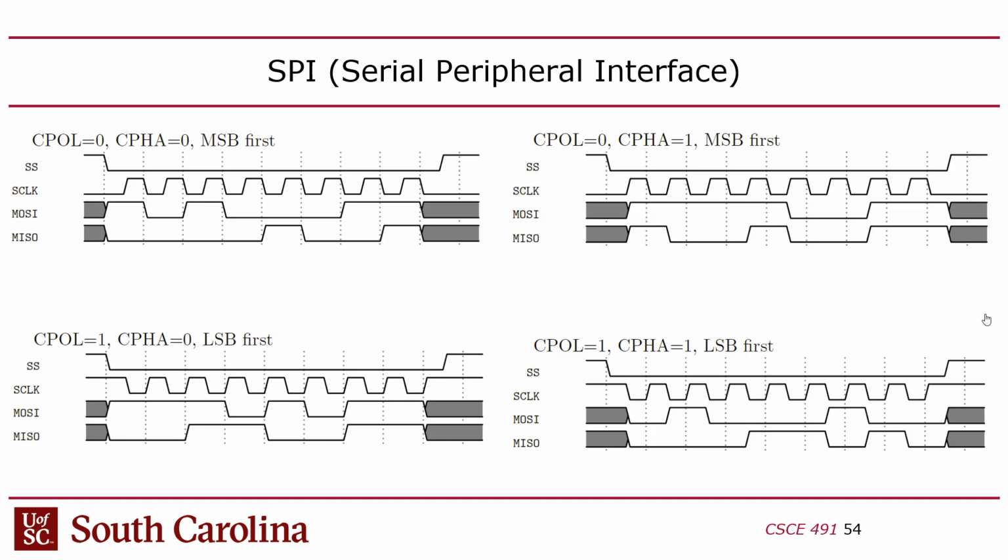But the worst case outcome is it could just be totally garbled, because every time you read, you're also writing. You're writing and reading the data at the same time. There's going to be a violation of the setup and hold time. You could end up with random errors, right, due to metastability on the flip-flop reading the data.